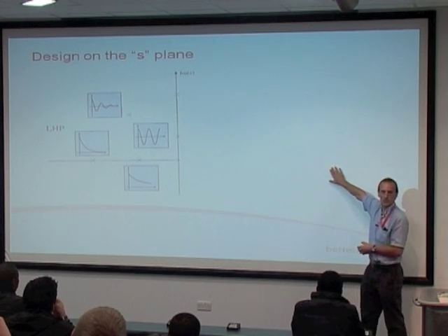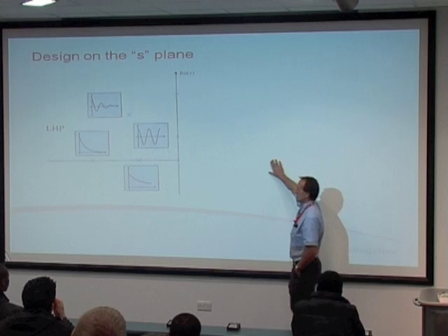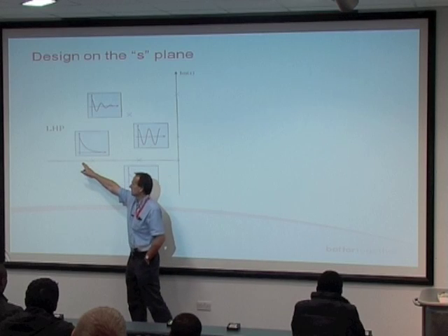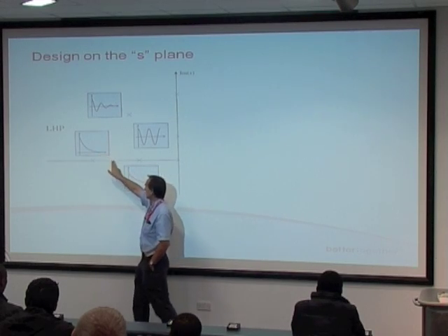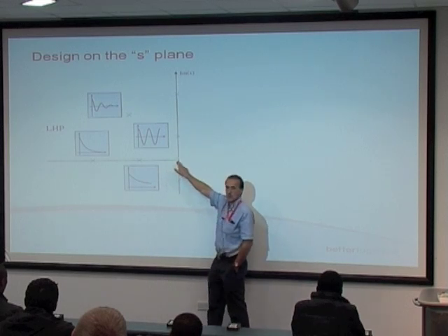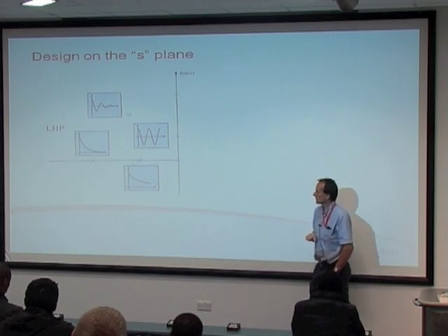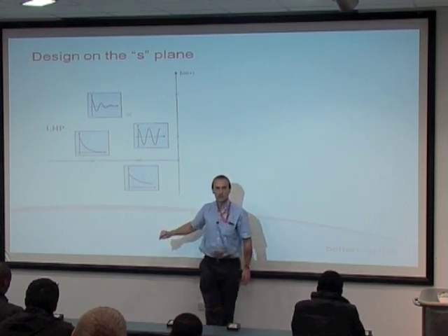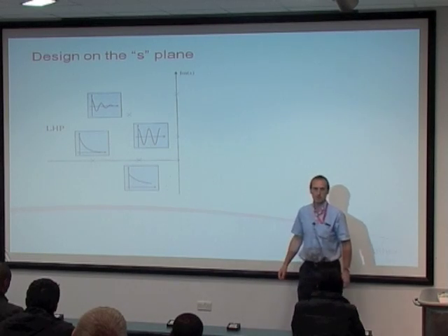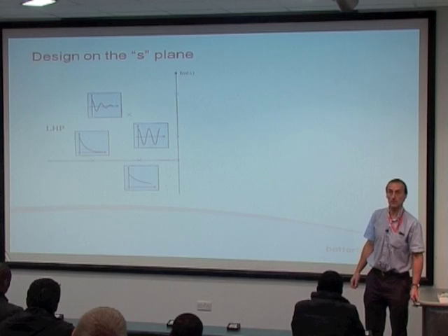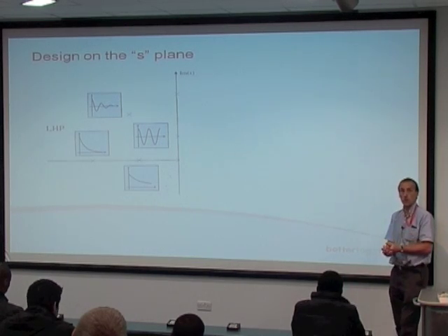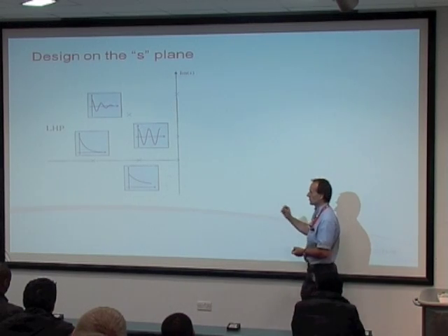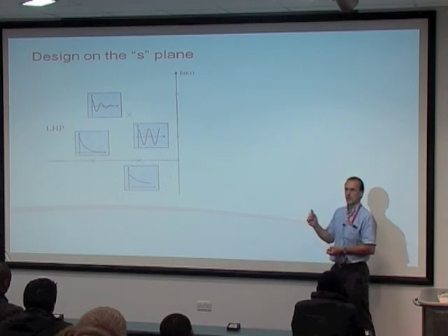What about this big empty space I've got over here? Just continue the story, okay? This is really fast and stable. This is slowing down and stable. This is my integrator position at the origin, where in response to an impulse input, it would hop up and then stay there. What do you think happens on the right-hand side? Yeah, they grow. Instead of diminishing, they grow. And if you think about where the pole position's coming from, what that implies is that we've got a negative time constant.